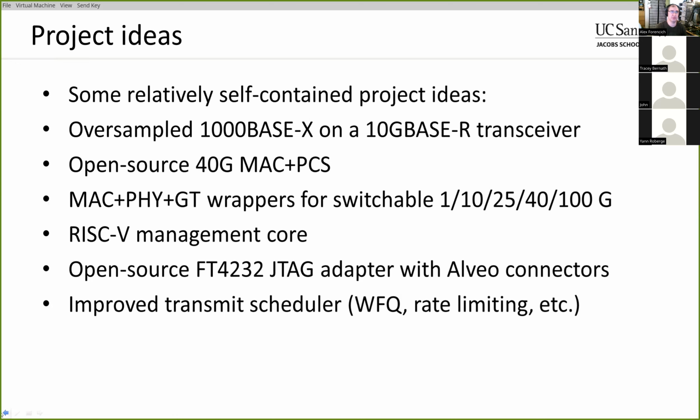Well, they make some very, very small RISC-V cores that could potentially be used. I know VexRiscv is highly configurable, so there's a bunch of different ways you can set that up, and some of those are quite small. I'm also aware of a core called SERV, which is extremely small because it is bit-serial. It's also slow, but it is stupidly small. I've seen some that are in the 15 to 20,000 gates or levels, so there are definitely small ones out there.